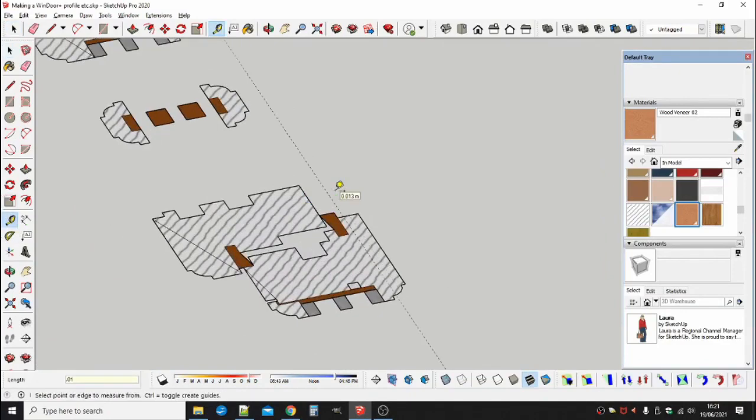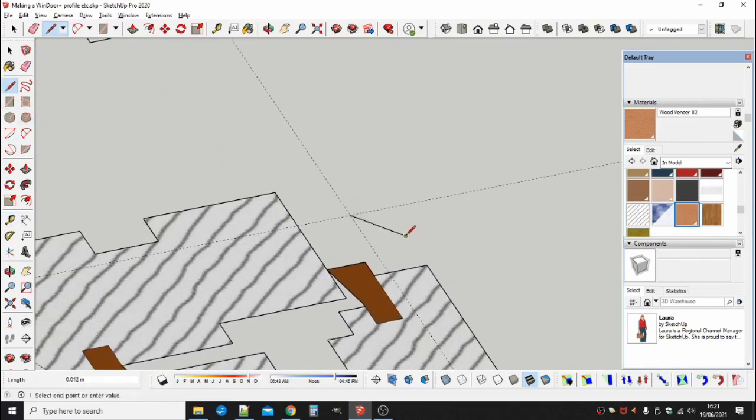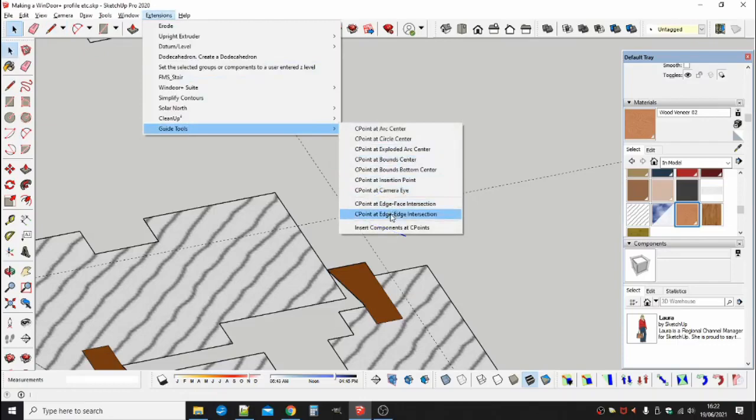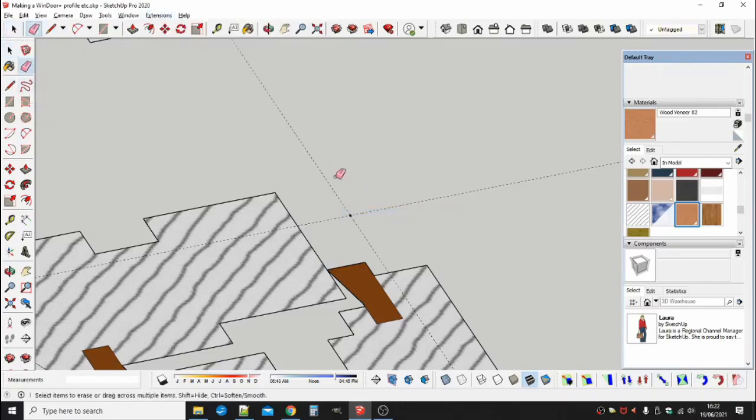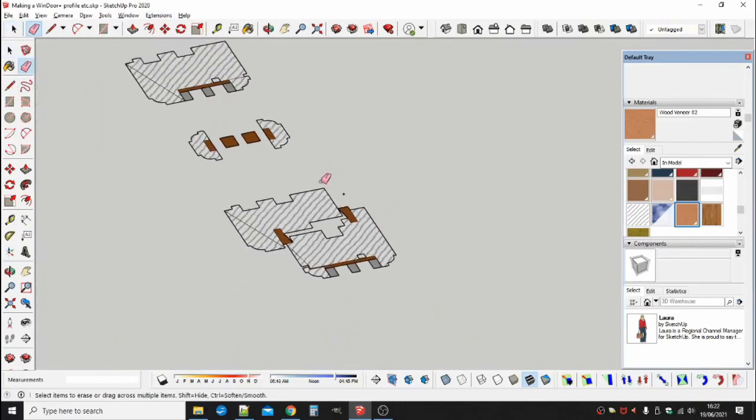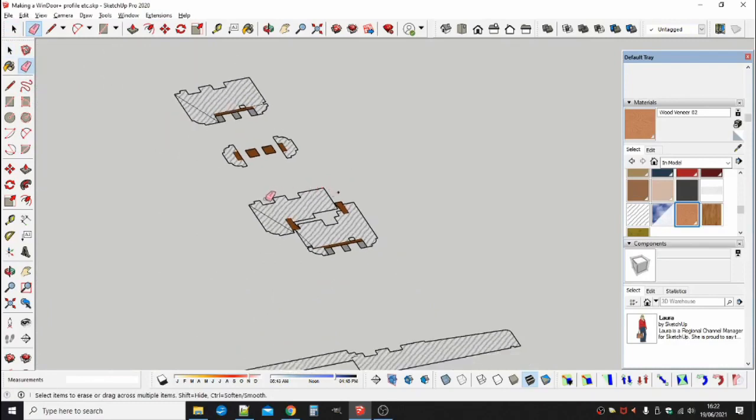Add a construction point at the hinge point of the opening sash. If you don't do this, then the extension will not be able to execute the open or close casements method. The next thing you need to do is to make some SketchUp components out of the faces.